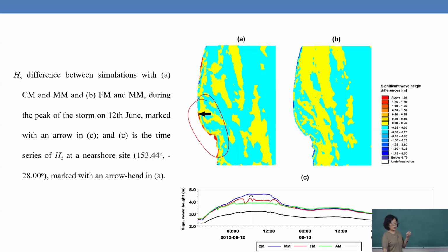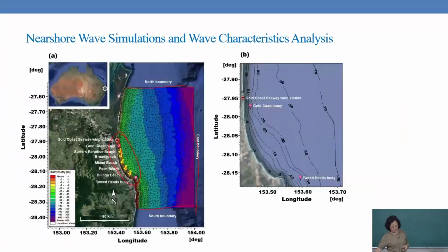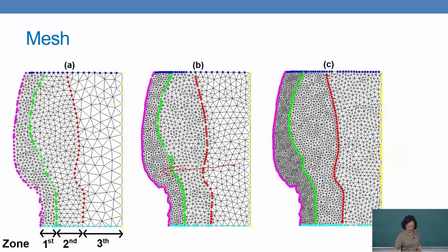The discrepancy is larger, so we have to get a finer mesh near the coastal area. That's what we are having. So you are able to see the coastal area, the mesh is finer. So that's our finer mesh, and all of that is based on the shape we follow, which is basically the bathymetry contour lines a lot.